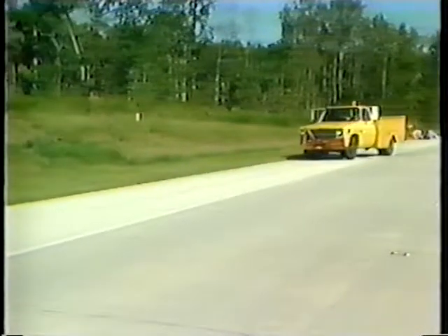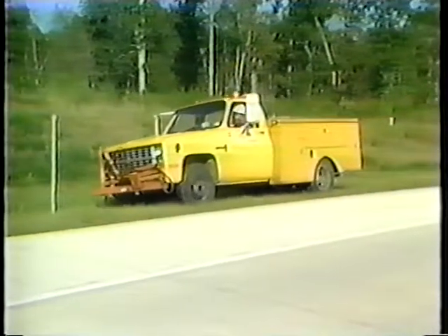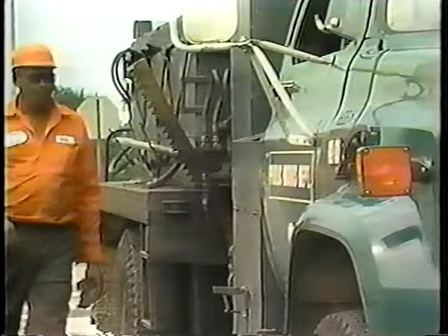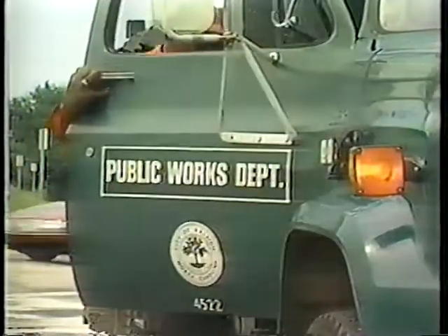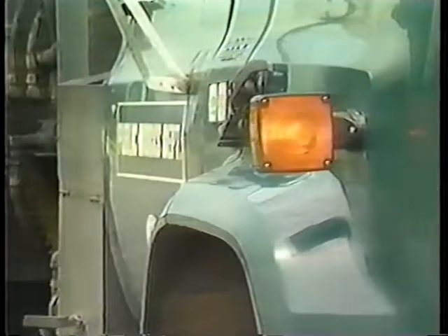Work vehicles in or near the traffic areas are hazards and should be equipped with flashing lights. The vehicle warning may be emergency flashers, flashing, strobe, or rotating beacons. High-intensity lights are effective both day and night. The flashing lights should meet the requirements of the agency that has jurisdiction over the street or highway. These lights should be used in addition to other channelizing and warning devices. However, in some emergency situations where the work may be in progress for a very short time, these lights may be the only warning device.